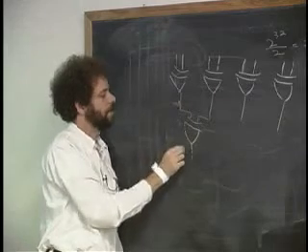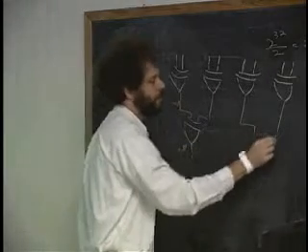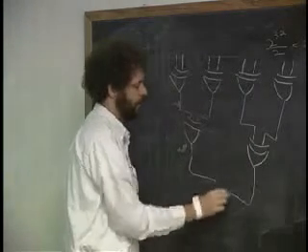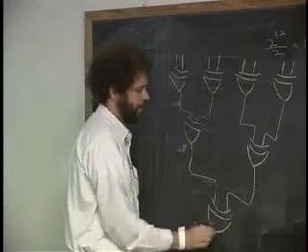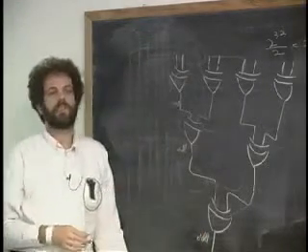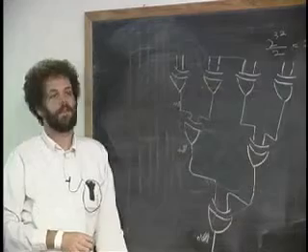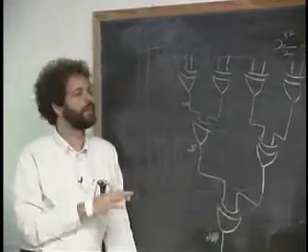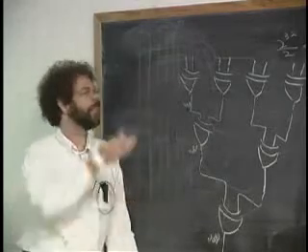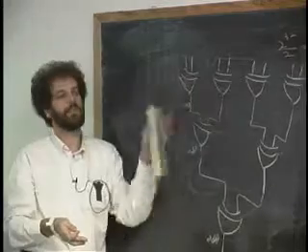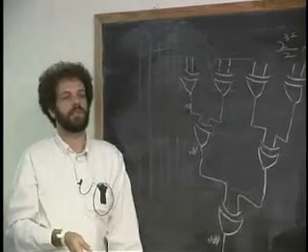This is saying odd. Of course, I can do the same thing here. And then I can take these two things, of course, and this tells me whether or not I have odd parity of 8 inputs. And so this is a tree. And it's a tree that is not, by any stretch of the imagination, sum of products form. It's not that I do an inversion and then an AND and then an OR. And yet it's only 3 levels deep. And it can handle 8 inputs.